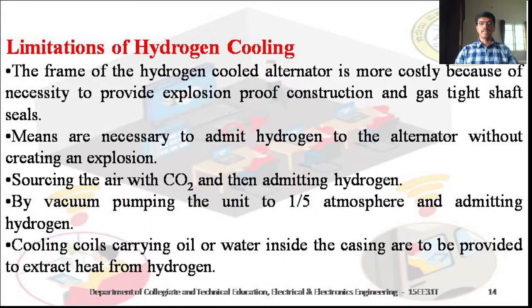And what are the limitations of using hydrogen cooling? Usually the frame of a hydrogen cooled alternator is more costly. The frame of the hydrogen cooled alternator is more costly because of the necessity to provide explosion proof construction.